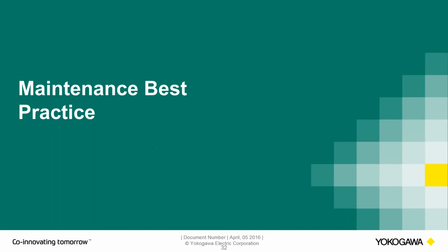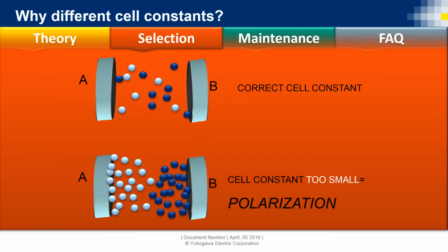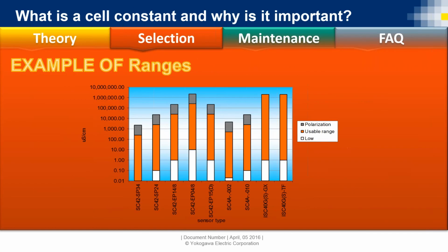And we also need to be aware, going back real quick, I gave you some values. Just because one competitor's sensor says 0.01 cell constant doesn't mean it has the same range from vendor to vendor to vendor. So we need to be conscious of what the actual measuring capabilities of a particular vendor's sensor are versus another vendor's.